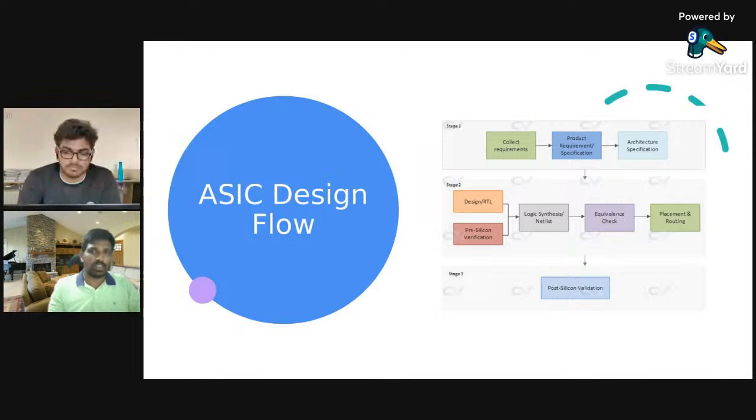Once you see all the pre-silicon things are done, that it meets the timing criteria, meets the power and performance numbers indicated by the project as per the spec, and there are no bugs involved, once you get the confidence on the product, you will deploy it for the silicon. And once there is a silicon available, not all the companies have in-house silicon. There are companies that give the silicon to other manufacturing companies like TSMC. So once the silicon is available, they go ahead with the post-silicon validation.